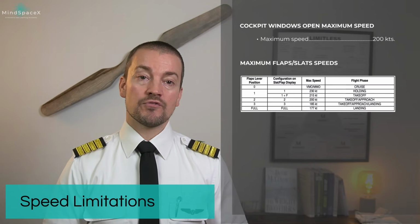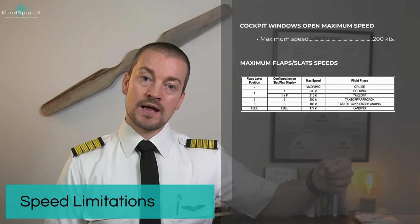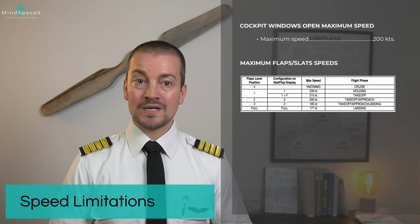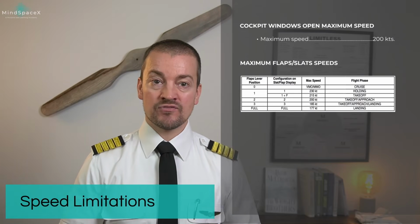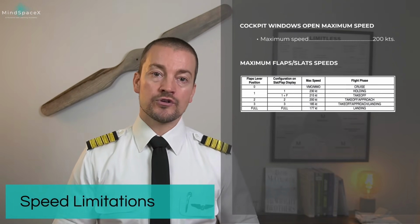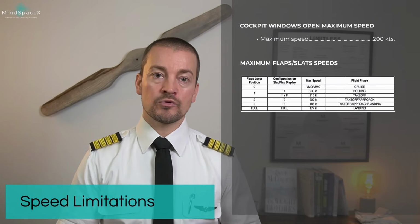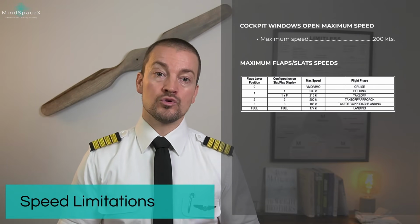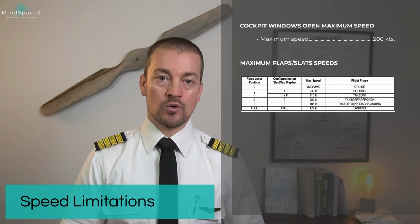The maximum speed for flaps 1, that means the flaps and slat lever set to position 1 and configuration 1 with only slats out, which is a configuration you will only experience in flight coming in and configuring for an approach, is 230 knots. It is used to slow down the aircraft from green dot speed in order for you to further configure the aircraft. It is also used for holding to get better fuel consumption during holding.